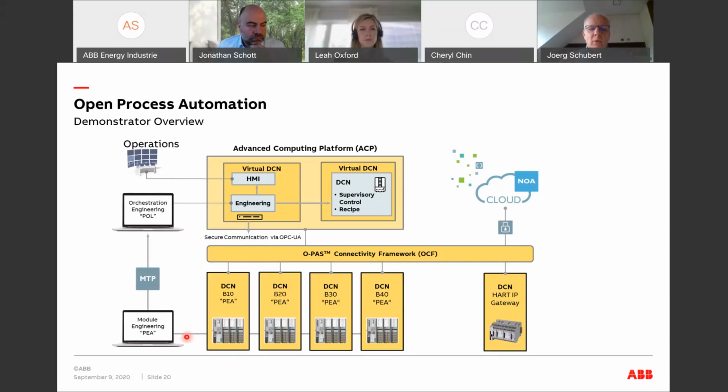In modular automation, you are specifying what's running in this equipment with its local automation in the form of services. So when you look at this physical equipment here, it has something like filling, it has something like heating, it has something like mixing, it has something like draining. So the key automation functions on the equipment are described in what's named the module type package.